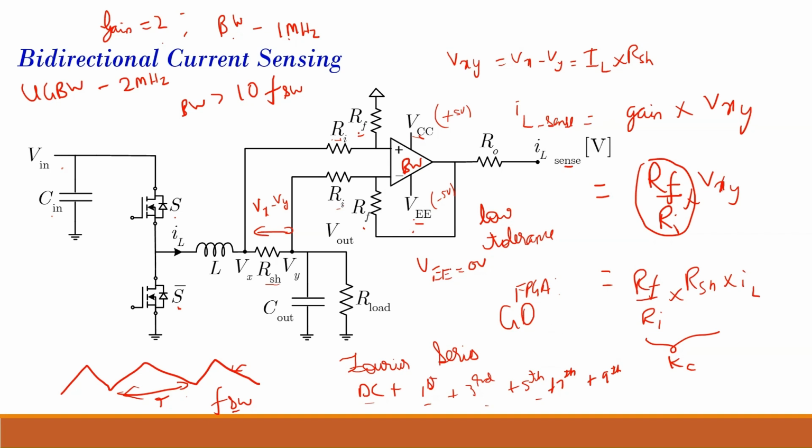So when you are actually making a board, you have to consider all these things. For example, you must consider that you're generating a 5-volt supply, and that 5-volt supply can be used for your gate driver. If your gate driver requires another voltage, then you have to use a resistive divider to step down the voltage. Also, the concept of isolation you'll have to consider if you're using an isolated converter or isolated sensing. These aspects come under hardware aspects, which I hope you will consider when you're making a PCB or a hardware prototype board.